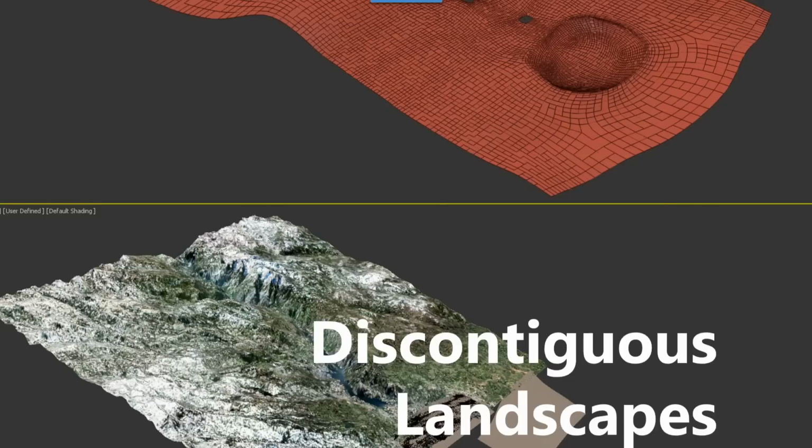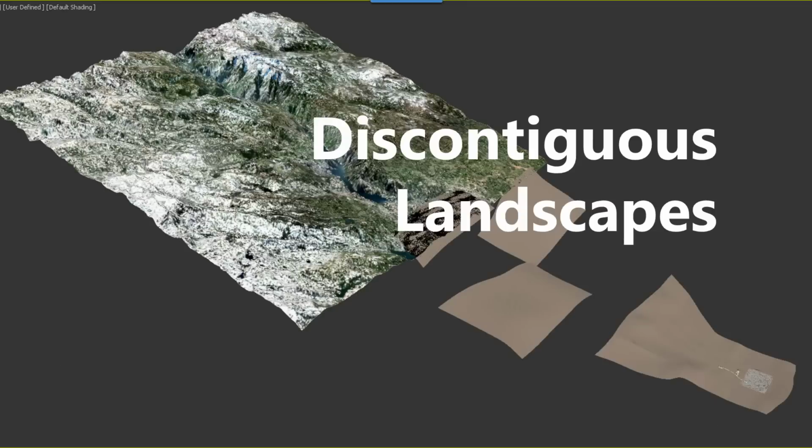If you are using that kind of displaced geometry, or geometry that's been produced by photo scanning the terrain, for example, then there are some tips to help make this geometry more manageable, make it produce fewer trees in the scenes. And one of the ways is to use discontiguous landscapes. So if you are seeing a scene that goes back some distance like this one, there's no need for that terrain to be continuous from right in front of the camera to the very, very far background. As you can see here, the area in front of the camera is just a small patch. And then we have 3 or 4 other pieces in the distance to scatter trees. And then way in the background, a sort of mountainous terrain just to fill in.